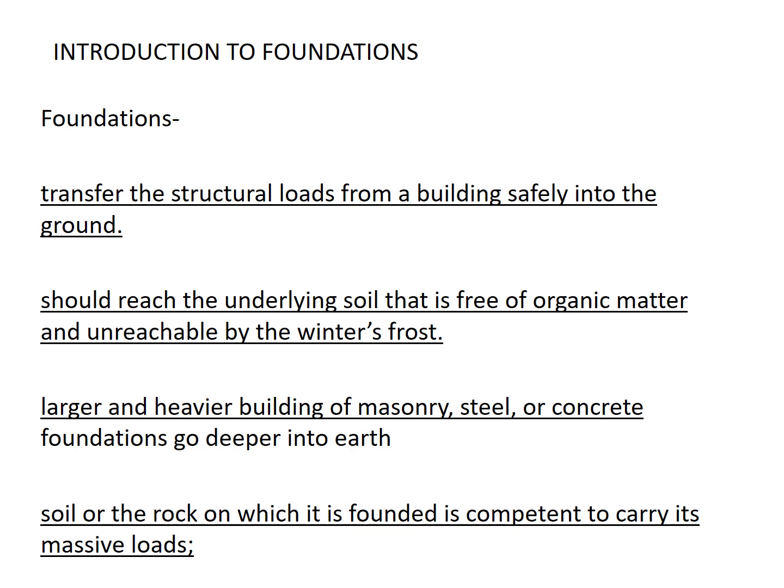A large and heavier building of masonry, steel, or concrete would require its foundation to go deeper into the earth, such that the soil or the rock on which it is founded is competent to carry its massive loads. On some sites, this means going 100 feet or more below the surface, because of the variety of soil, rock, and water conditions that are encountered below the surface of the ground and the unique demands that many buildings make upon the foundations. Foundation design is a highly specialized field of geotechnical engineering.